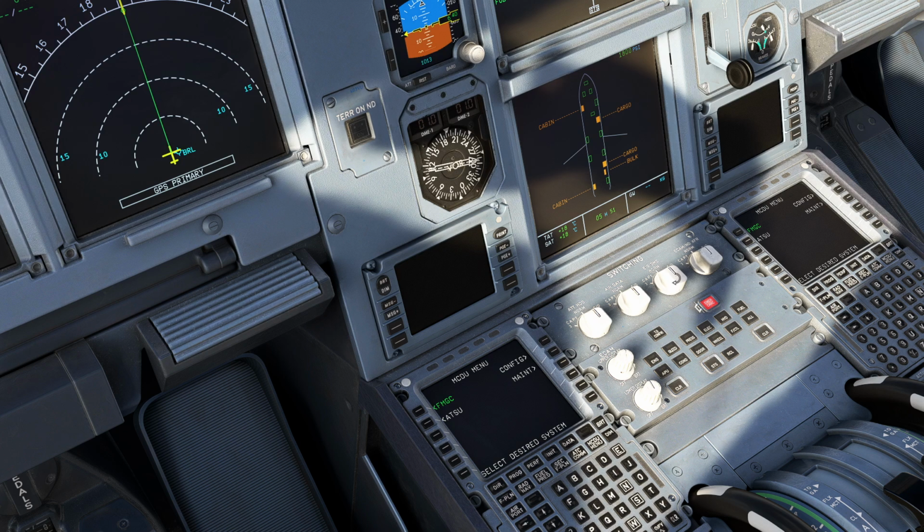Through this switch, the pilots can replace DMC1 and DMC2 with the DMC3 for any selection. Another switch is at the right side of the EIS DMC switch with the name of ECAM ND transfer, which is a switch on the right hand side of the switching panel that enables the flight crew to transfer the ECAM system display to either the captain or first officer navigation display.